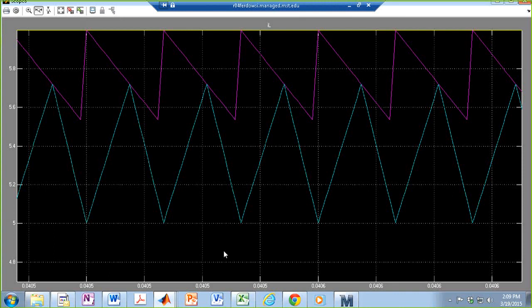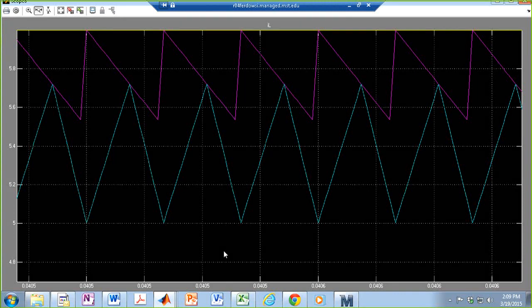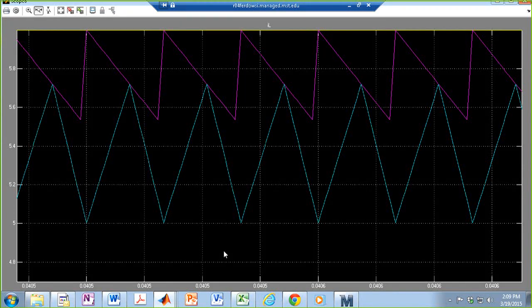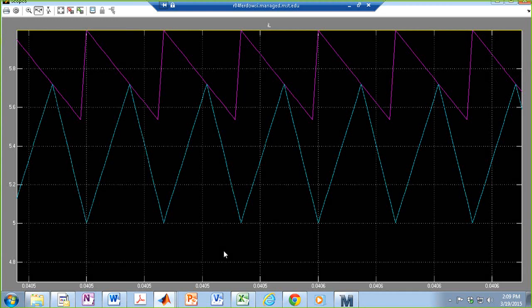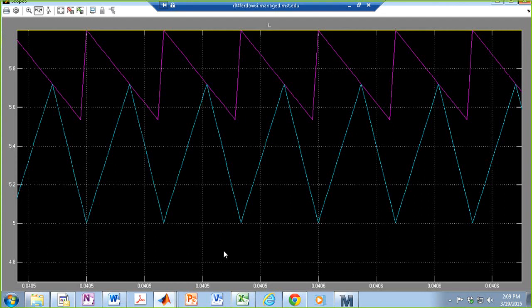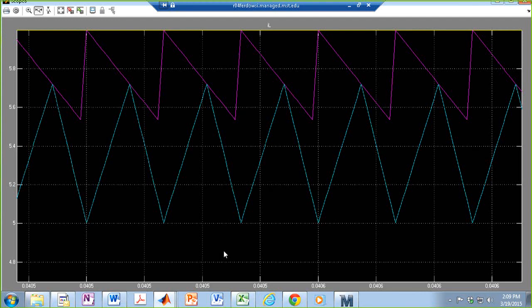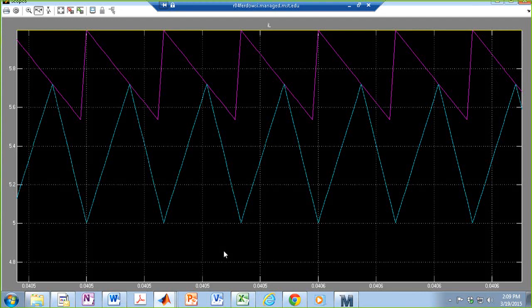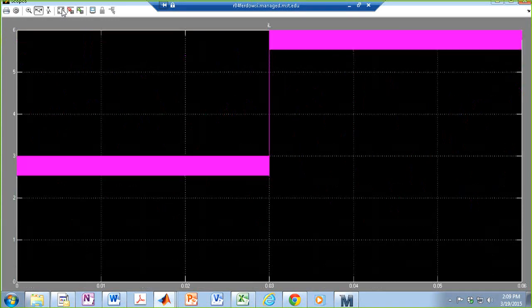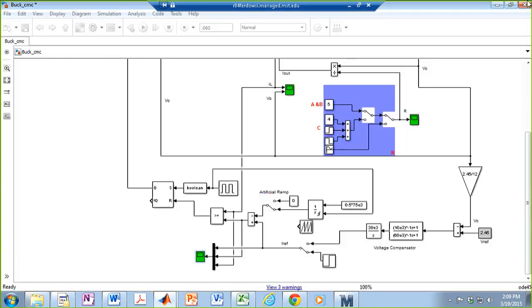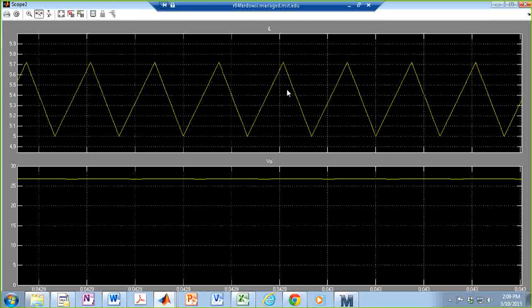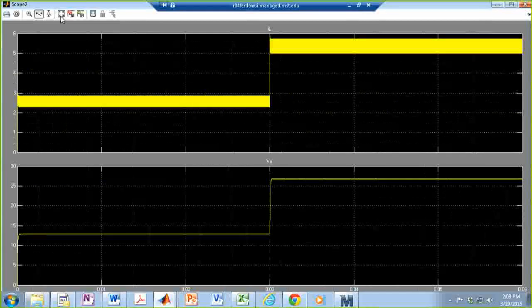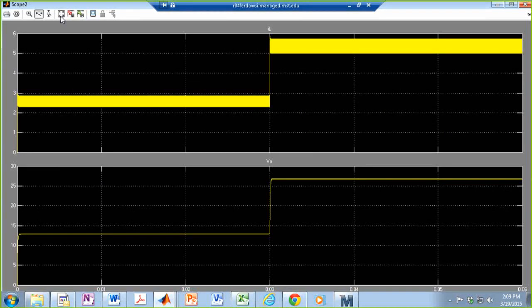So I'm going to post this on Blackboard. If you want to mess around with it, play around with it, go ahead and do so. And also I have a compensation network that we are going to design today. And again, look at the simulation one more time in case you want to close the loop and basically regulate the output voltage, because right now the output voltage is not regulated. You can see I commanded the inductor current to increase, therefore the output voltage increased, the second trace down there. All right. So this was to show you a demo of this chaotic behavior.